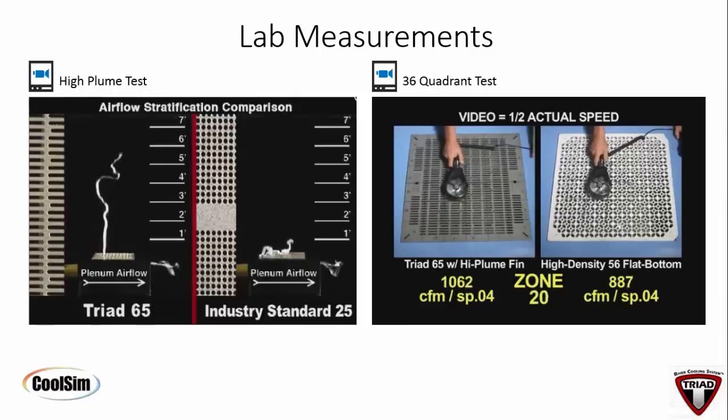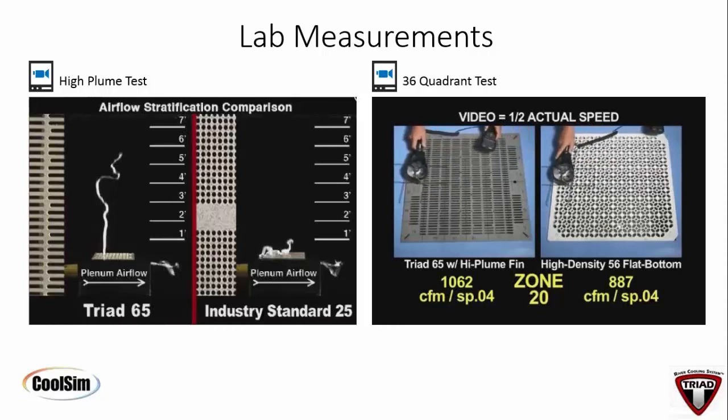Just moving it over 4 inches, you see a 500 CFM jump, which means we've got a wave effect going on. And then the final move, to the front of the panel, is where you see this negative. Some of the testing analysis that Paul's group did actually validated what we were seeing live.